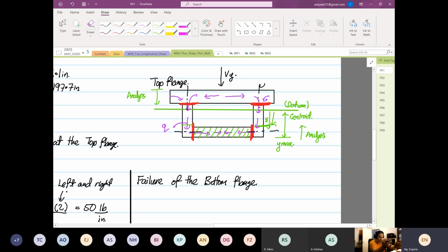So that is why, when we look at the first moment of area, we only consider the bottom flange. Your y starts from maximum, it slowly retracts. At a certain distance it covers the entire area of the bottom flange. The web area is not covered yet until y is equal to 0, then the entire web is covered. For this reason, you only consider the first moment of area of the bottom flange.